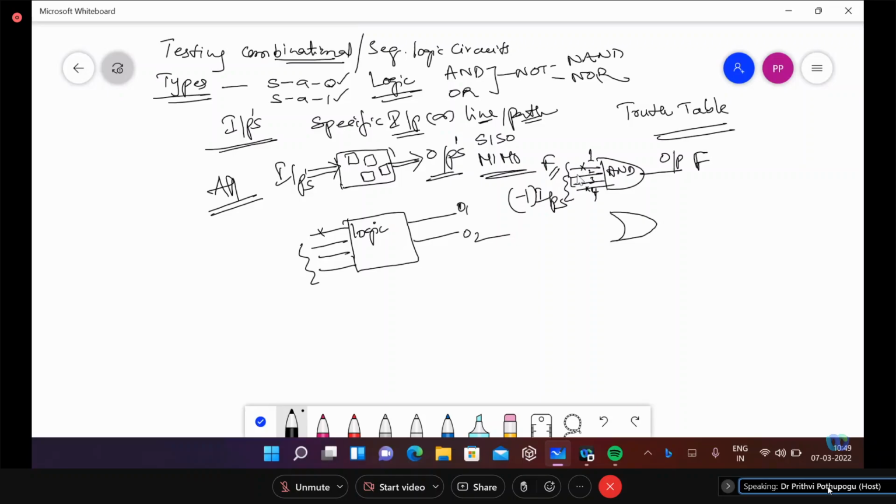I cannot make the other inputs false, because if any one of the inputs other than 4 is false, it straight away makes the output false. So see that all the other inputs for an AND gate are logic 1, except the one you are testing. Then you will be in a position to find the response of the system due to this input alone.